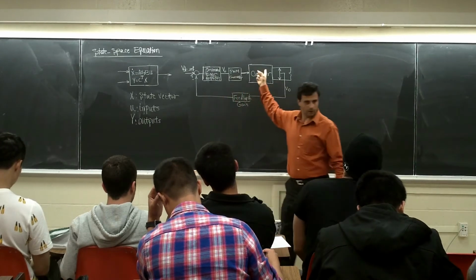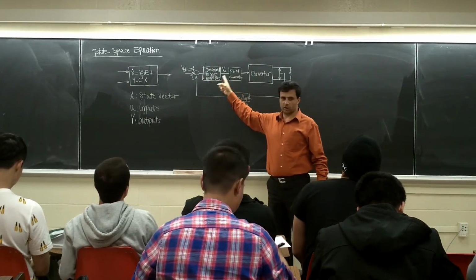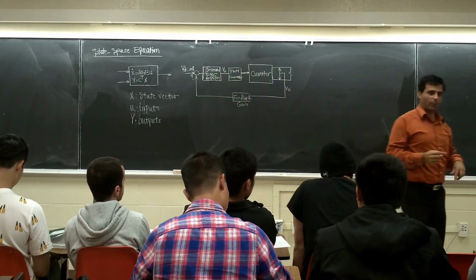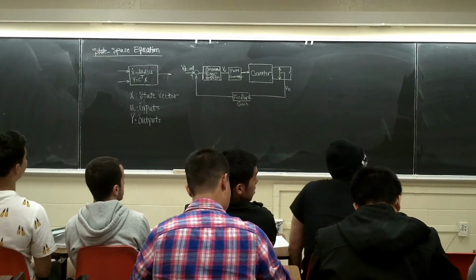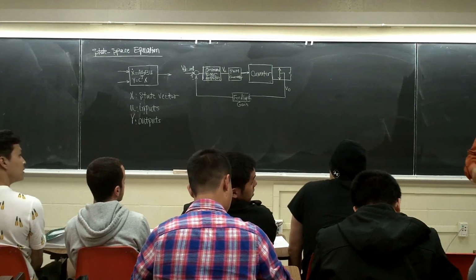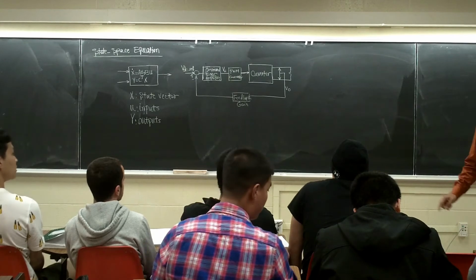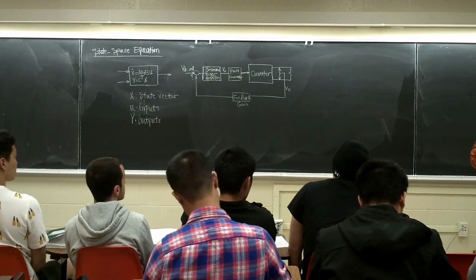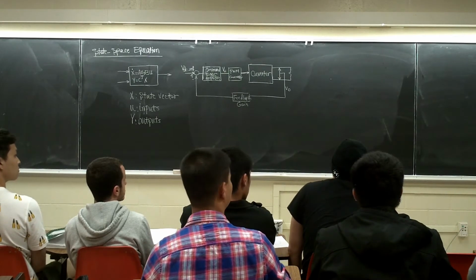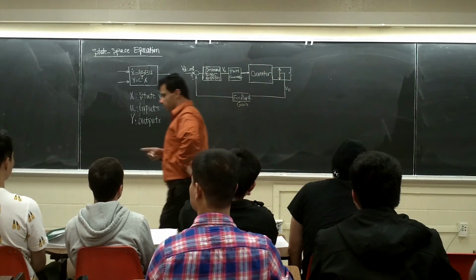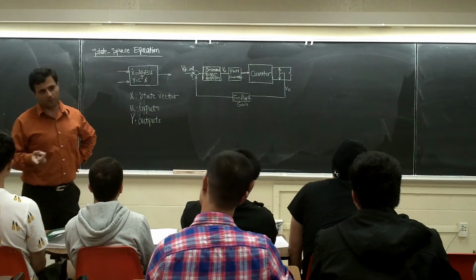After we have this, and we say what the structure is for these two, we can put the models together. Now we'll tell you guys, go design the value for this error amplifier. Go select those RC values. Or if it's a PI, go select the PI values for this one. You can go back when we finish this. If you are interested, the one with feedforward is a little more complicated to get the model for, but if you are interested, do it.